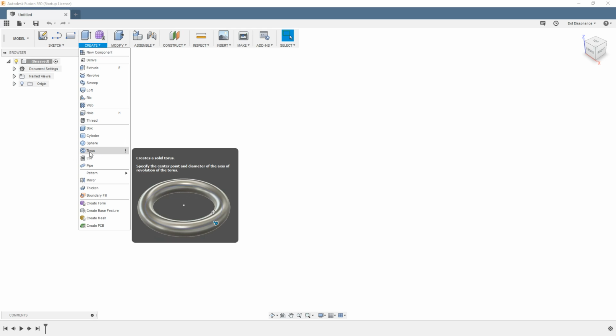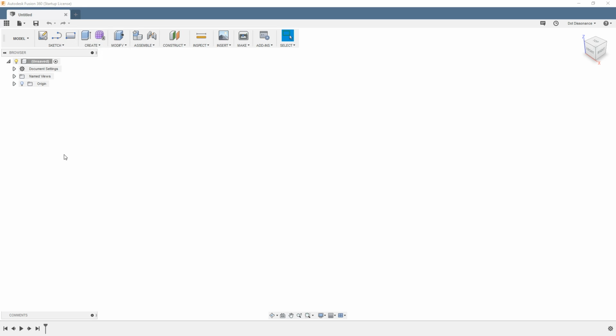Essentially 3D sculpting. What we want to do in our CAD engineering type design is create a sketch first. We need to create a two-dimensional shape called a sketch, and then we take that two-dimensional shape, which will be in this area right here, and thicken it up somehow or another, right? Typically it's called extrude. CATIA calls it a pad, so whatever.